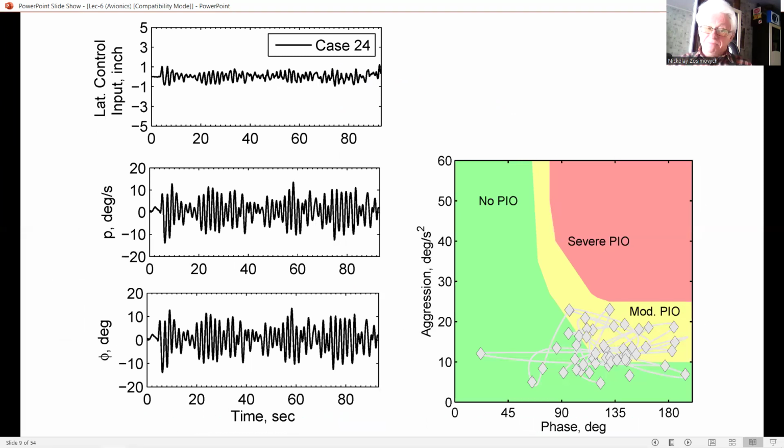Mention has already been made of the carefree maneuvering characteristic that can be incorporated in FBW systems. I hope you remember this term, FBW, yes? Fly by wire. This is achieved by continually monitoring the aircraft state and automatically limiting the authority of the pilot's command input by means of a suitable control law, which takes into account the aircraft's maneuver boundaries and control limits.